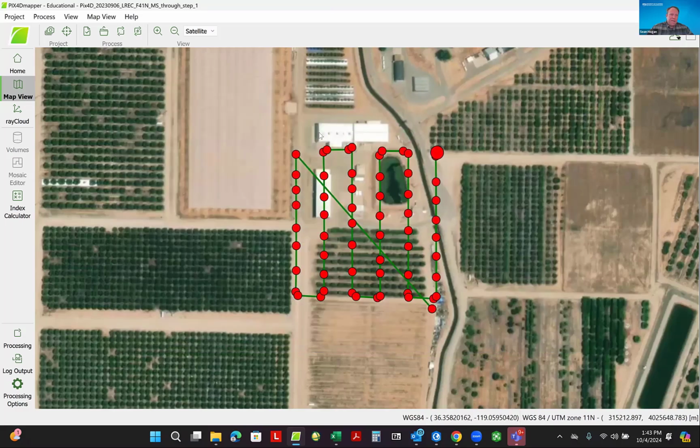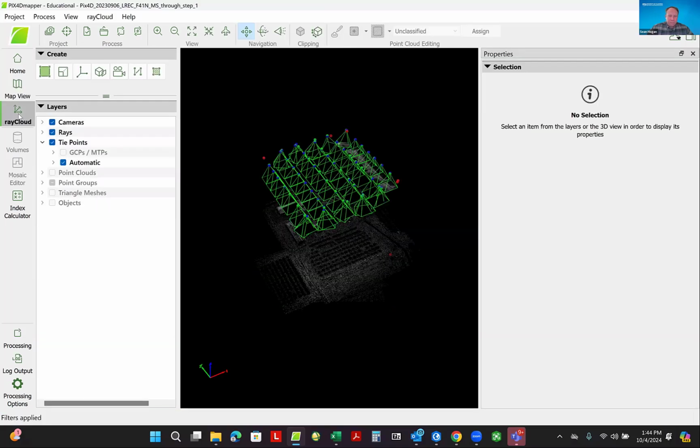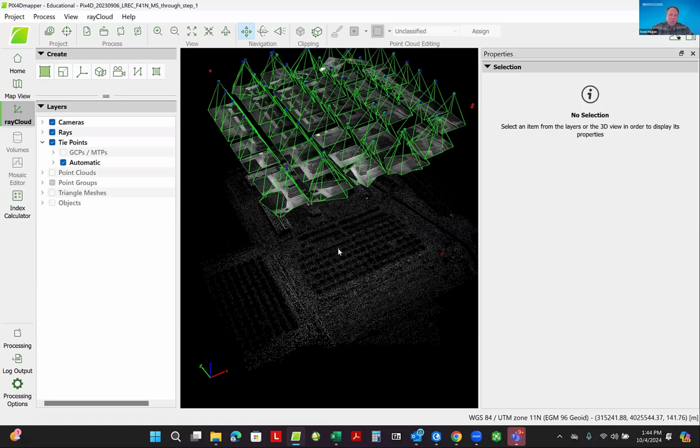Again, that would be the first thing that I would look at. And next, I would add in ground control points to lock my imagery together. What I would do before that is go to the ray cloud. The ray cloud is the 2D points or 3D points that are matching these imagery together. When I said that I would come back to how it re-engineers the positions, being the difference between the blue and the green point, this is how.